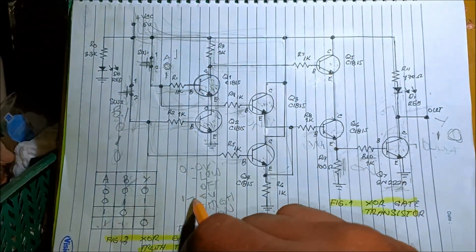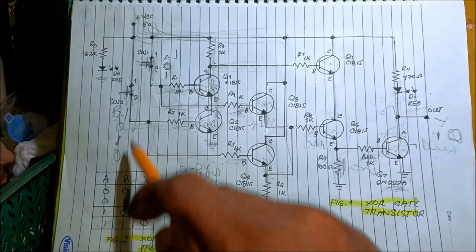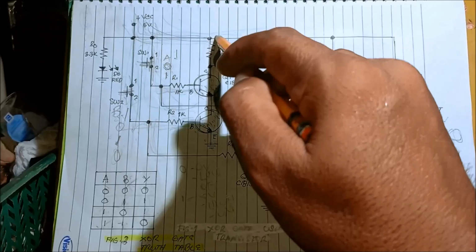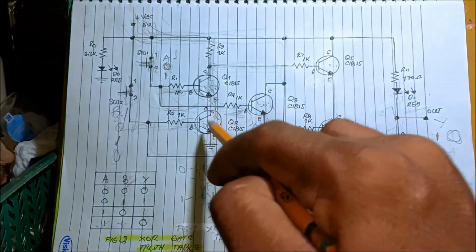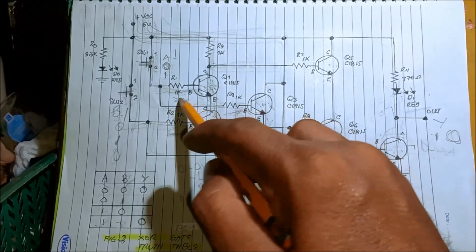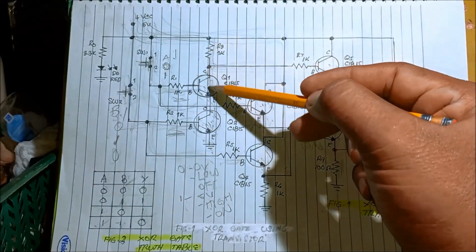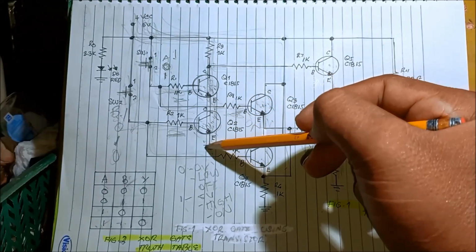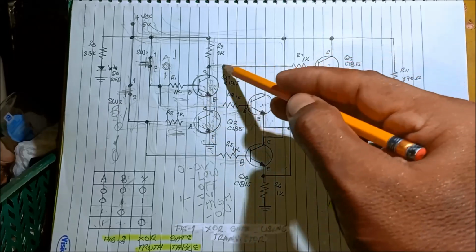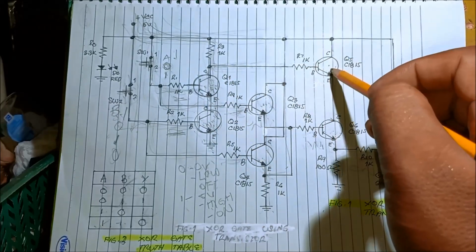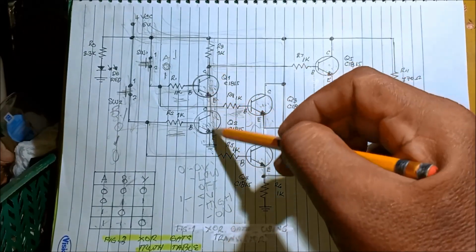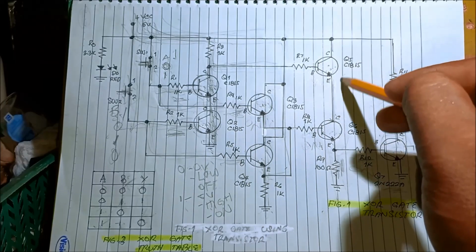That is the logic level high, and the current flows into the collector to emitter, then to the ground, because we're injecting a base current to this transistor and to this transistor. So the current flows directly to the ground. If it flows directly to the ground, there's no current that flows into this transistor, making this turn off.